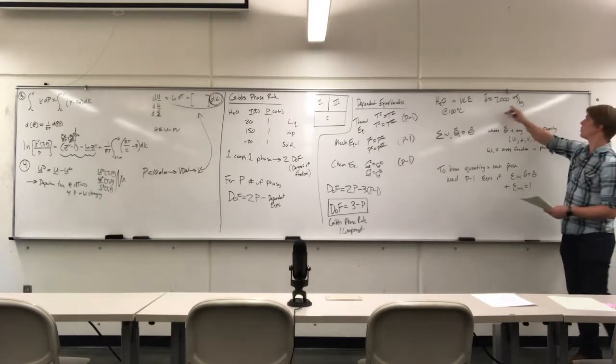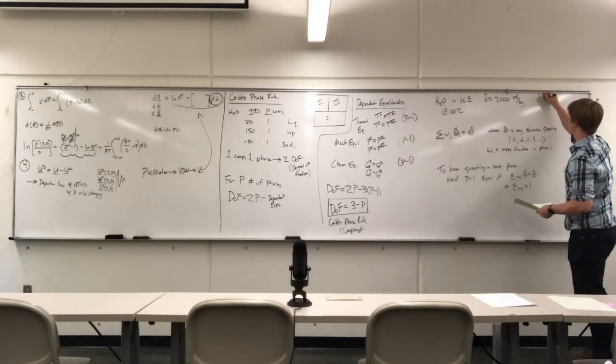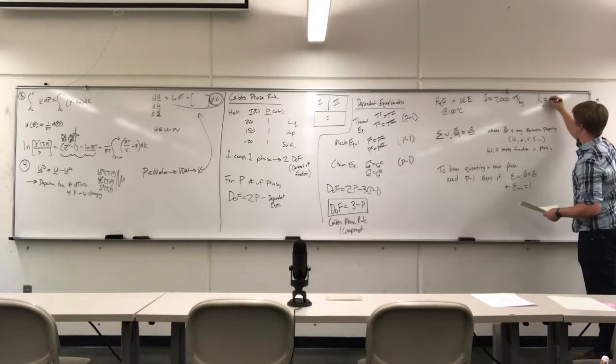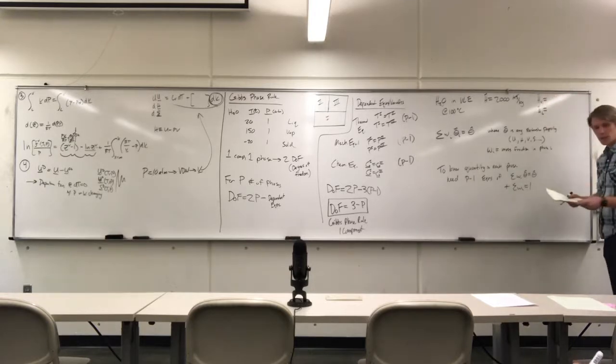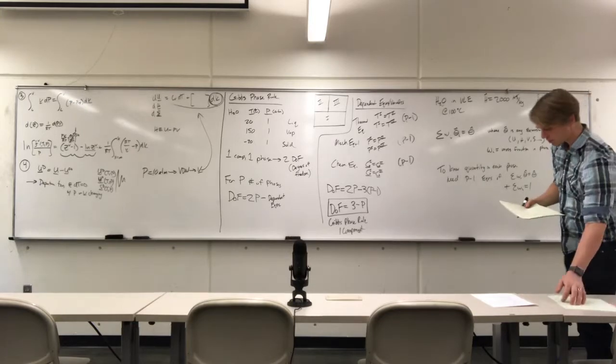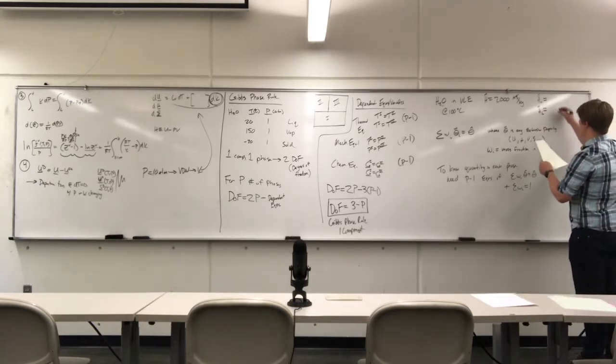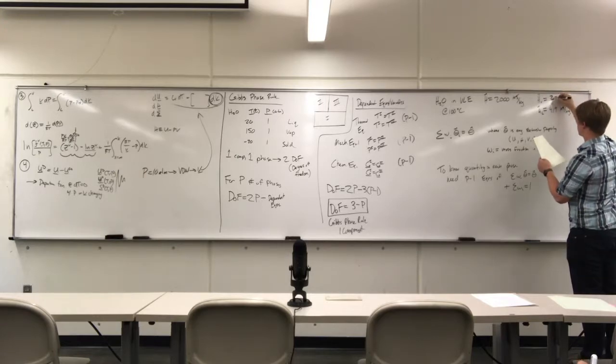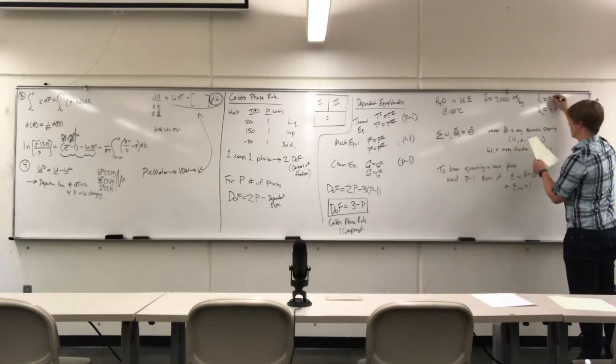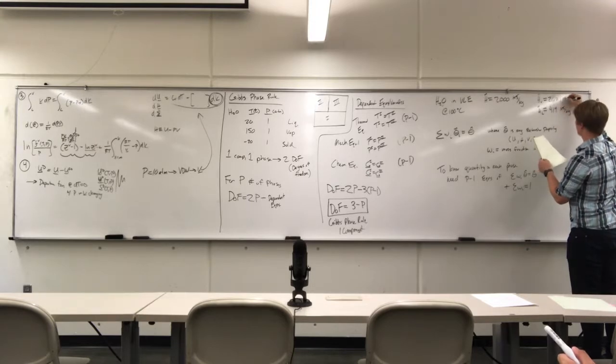So in this example up here, if the enthalpy of the vapor and the enthalpy of the liquid are found in the steam tables for this set of conditions, the liquid enthalpy is 419, and for the vapor is 2671.